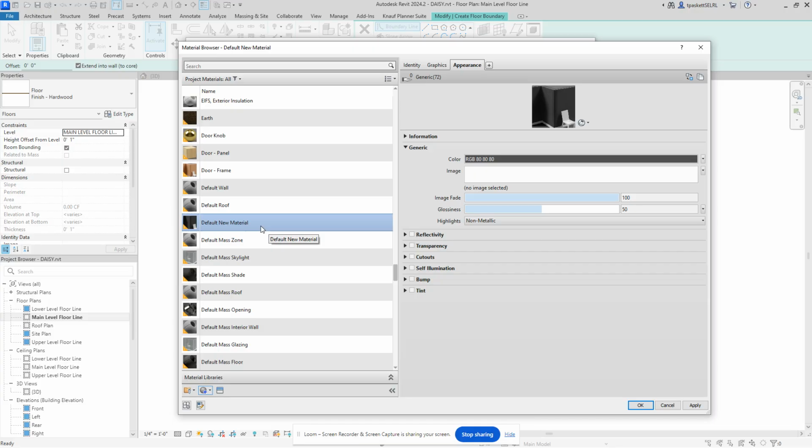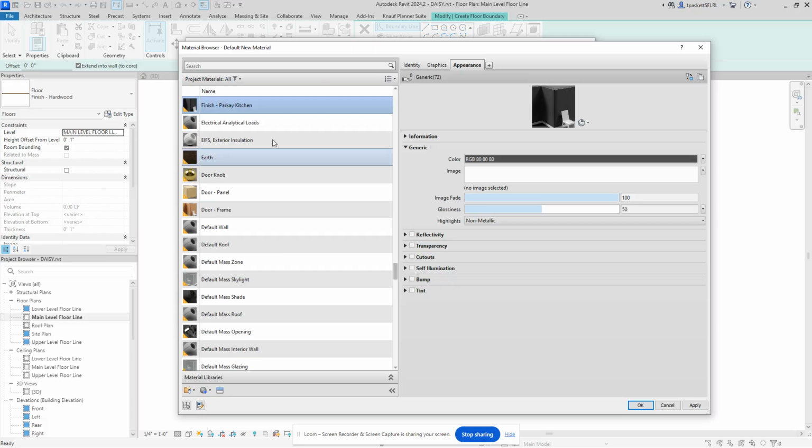So at this point, before we move on, we right click and we rename it. And this is finish RK. And I put the room on there so I know where I've used it. It's kind of what I do. You can just go with what the flooring is or the material. A lot of the kids will just put the color of the carpet that they have on there. And then you have to hit enter. So it doesn't automatically save at this point. You do have to hit enter, and that locks in that name.